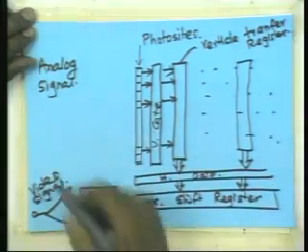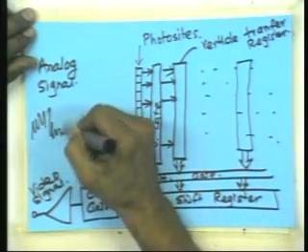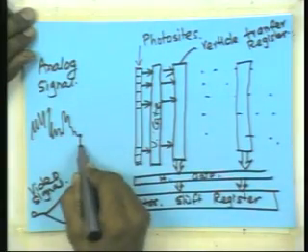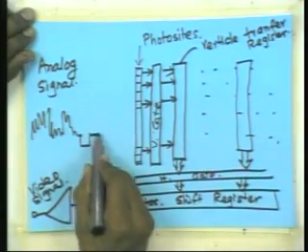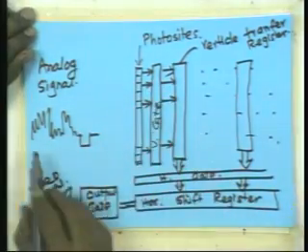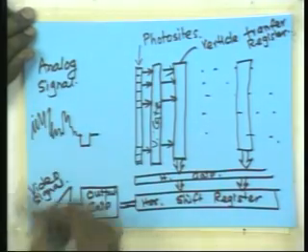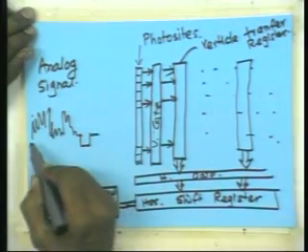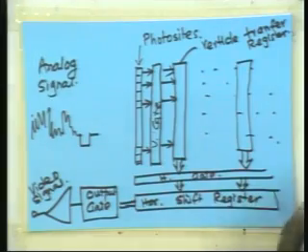Typically it will look like this, depending on the image, and then after each frame there is some blanking time, and then the whole thing repeats. This has to be interpreted with each of these representing a line. If you want to generate an image frame or a digital image matrix, then one will have to sample these and take out digital values and store them away. That is the task of what is called a frame grabber card.